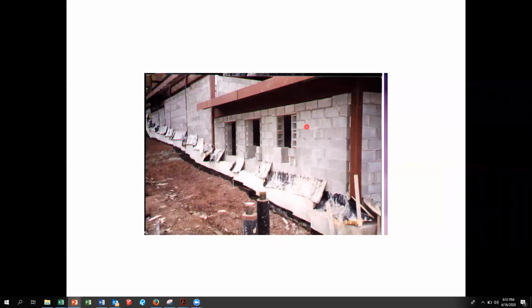This is the outside of the building. What do you got here? That's a temporary shore, right? Temporary planking for the bond beam. Okay, it looks like it's got a little bow in it because it's not that rugged. It'd be like a 2x8, only we call it an 8x2 because it's lying flat. These blocks are just used to hold this shoring up.